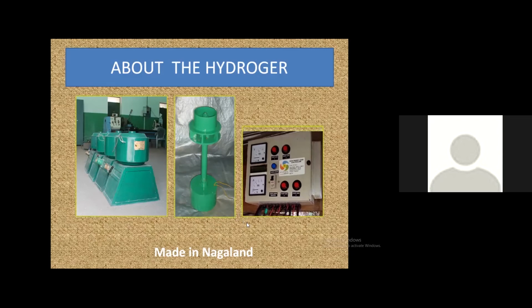These are small portable machines, and the reaction one we are in the process of developing, but our main installation so far has been with the impulse type. For those of you from the technical side, the ELC is frequency based and has 4 dump load arrangements.